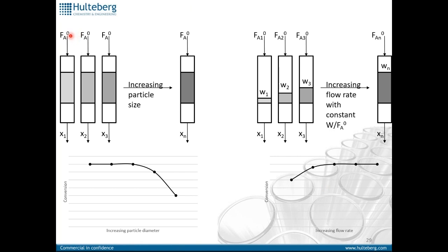So if you have a flow rate going through the catalyst, you have a certain conversion, you have large or small particles in this case here, and you make the catalyst particles larger and larger and larger, and you get different conversions. And if you start from the end of large particle diameter and you, for instance, make the particle diameter half of what you had and your conversion increased, then you know that you had a gradient.